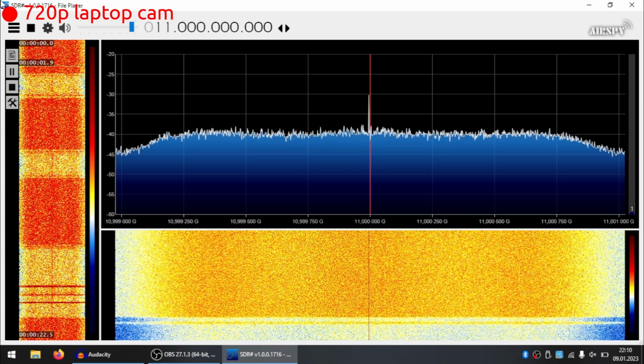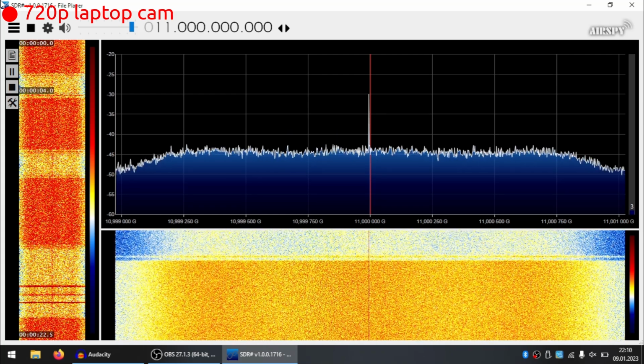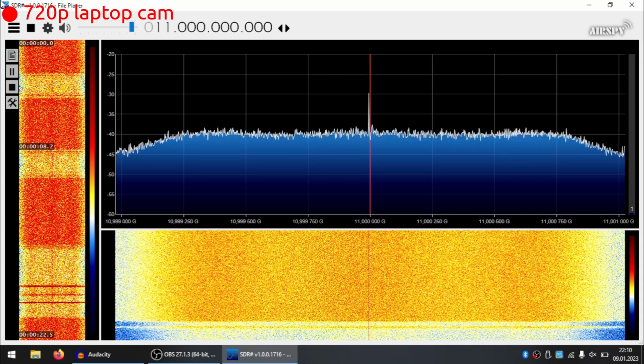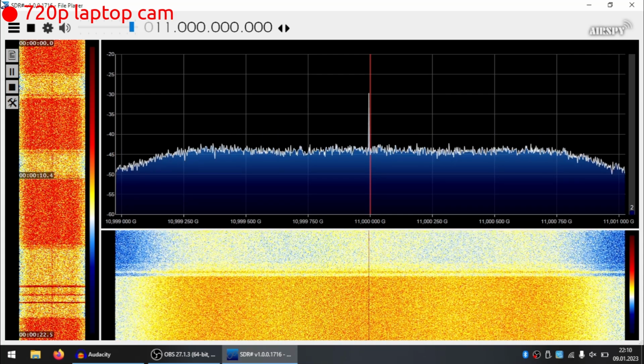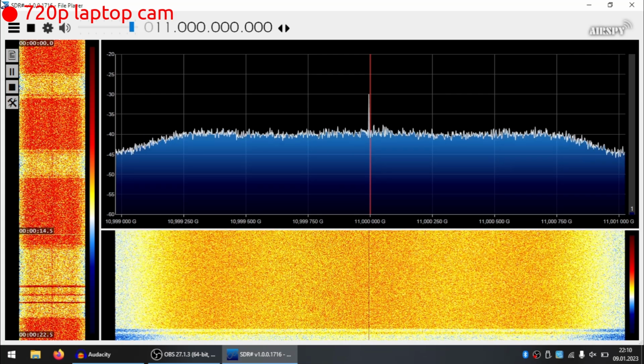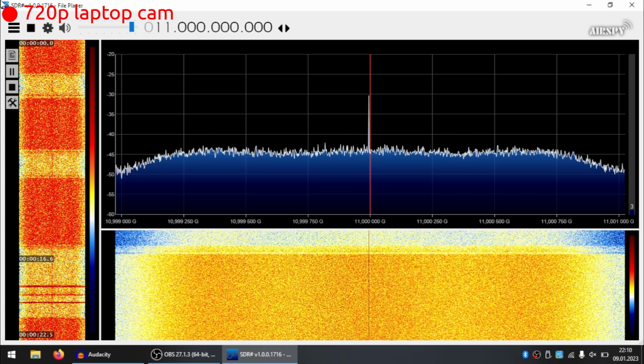Staying at 11 GHz, which is inside the LNB's rated frequency range, you should be able to notice the noise floor level changing as you aim the dish around, especially increasing as you aim at the ground. This is the LNB picking up RF noise reflected from the sun. Aiming directly at the sun will produce a similar, stronger effect.